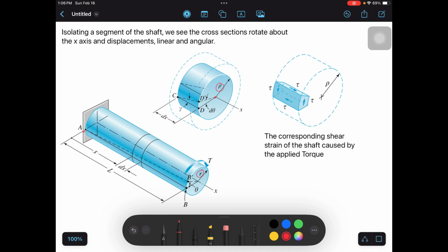Next, we apply a load, which is a torque, a twisting moment. Where does it twist again? It is about the x-axis. So when you twist it clockwise, if you have a line segment here, let's call it CD, when the torque is applied, it will twist, and of course you expect our material to twist. So we will have a point D prime, since it twisted. The center point is fixed. It will not move. Only the surroundings of the shaft twist.